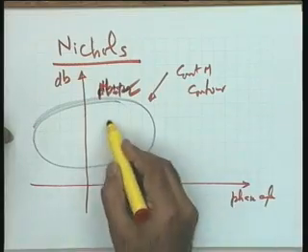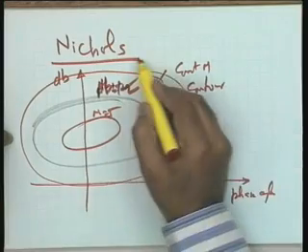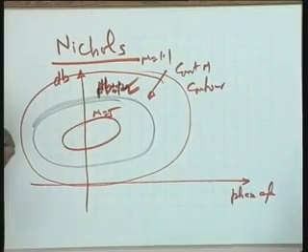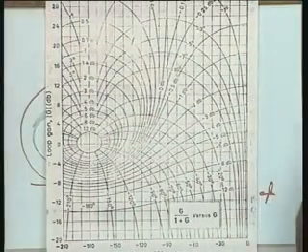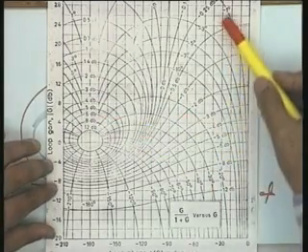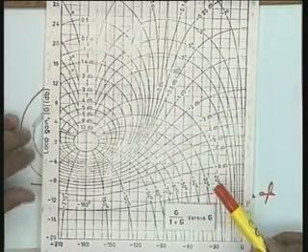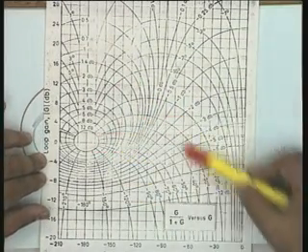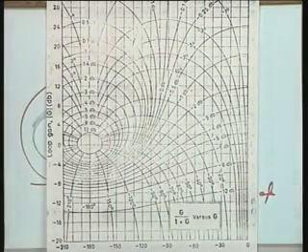For example, take some other value, let us say that this is M equal to 5, I take another value, this is M is equal to 1.1 and so on. These are the values, and now I think I can project the Nichols chart. This is the standard chart as suggested by Nichols. You will find this chart a little clumsy because there, in addition to the magnitude lines, the phase angle lines are also shown. If you ignore these phase angle lines and look at only these magnitude lines, then the plot will be less clumsy, you see.